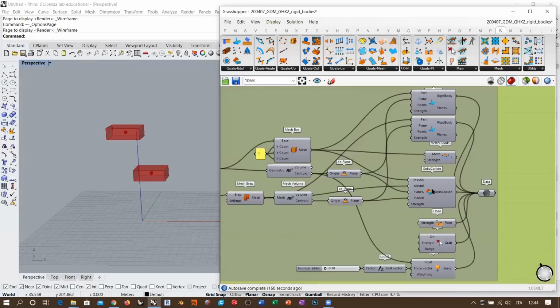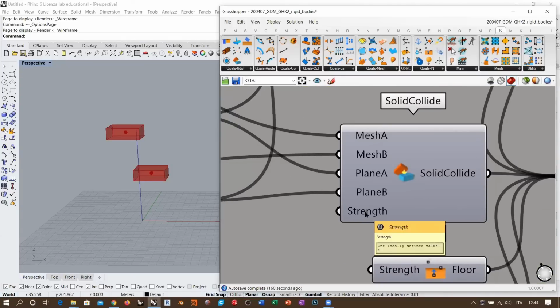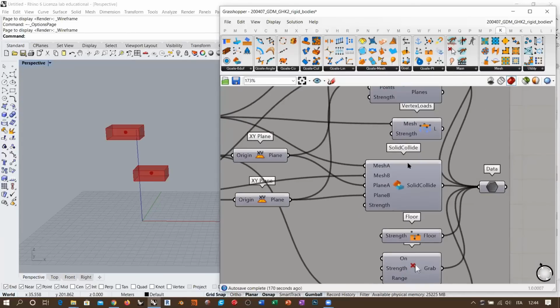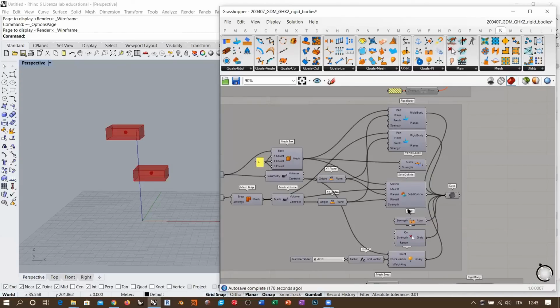And one consideration when you start to work with collision, the strength. Now, I wouldn't change the strength in a normal balance between the strengths in Kangaroo. You see that here I'm not touching any strength, okay? So unless you do something weird, like tweaking the strength of some goals too much, then in that case you might want to tweak also the strength of the collision.